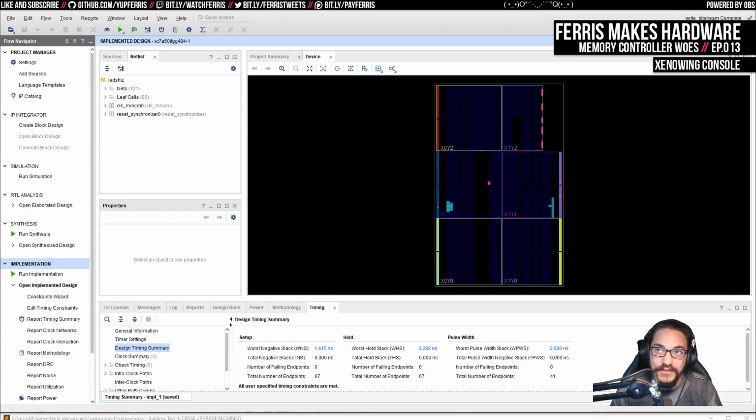One of the things also is that this memory is DDR, so it's running at double data rate. And so to run this particular memory chip at 300 megahertz, which is its minimum, you need to generate a controller IP that's either half or quarter rate. And with this particular board, they only let you generate a half rate interface, which is 150 megahertz. And 150 megahertz, I think, is actually quite fast for this particular part.